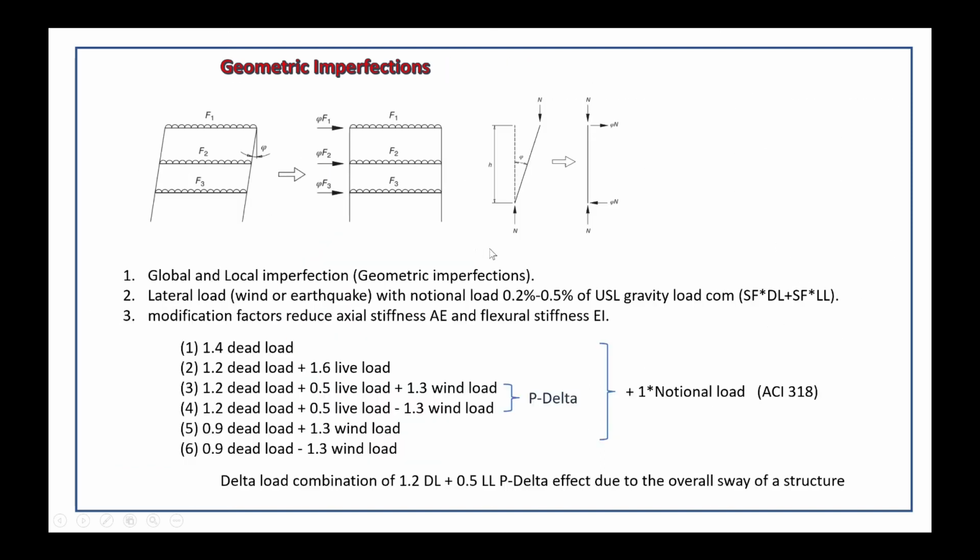And I discussed this in this slide. You can check to apply P-delta analysis. You must include the imperfection of the structure, must include the global imperfection and local imperfection, and don't forget the combination with the notional load.